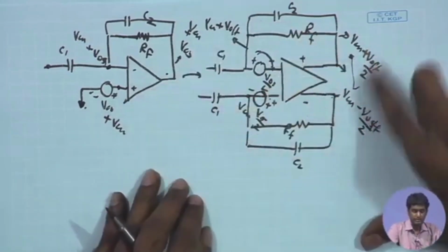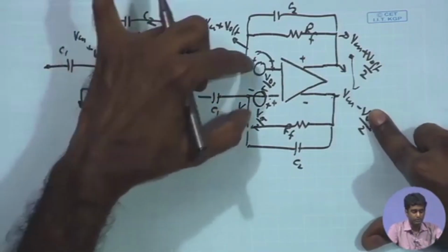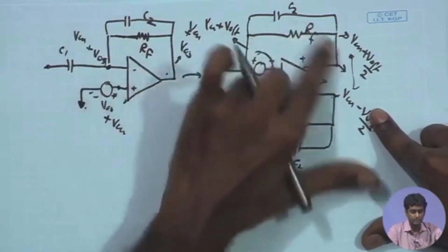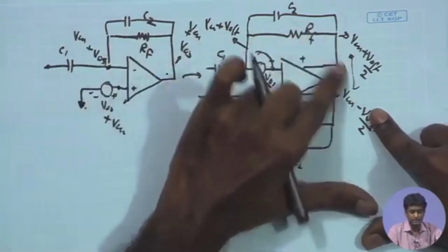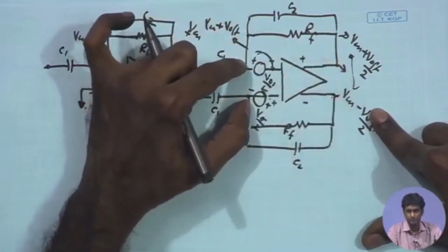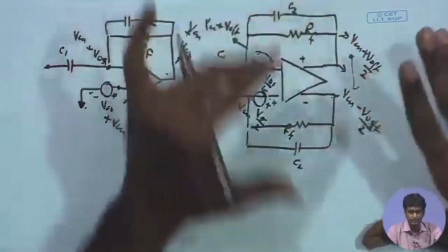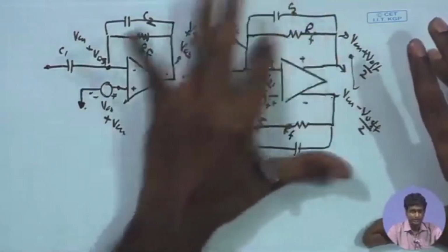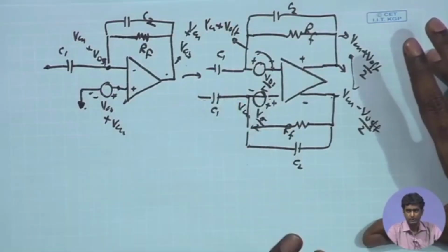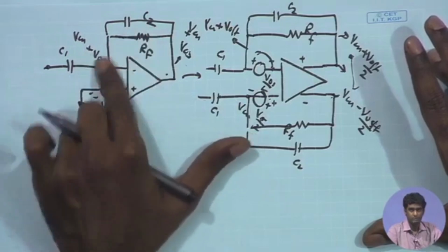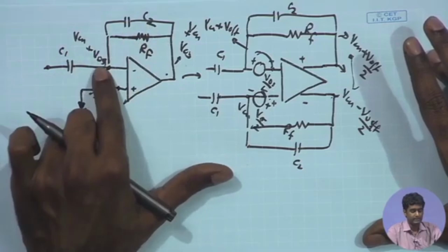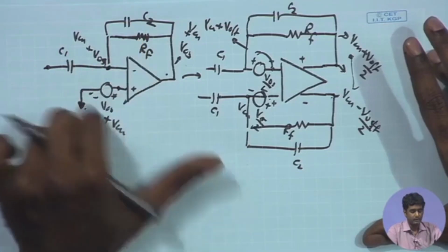So you have the difference just given by the V offset, corresponding to the effective input referred offset of the amplifier. In the case of resistive feedback, the difference between the outputs is just equal to the offset voltage, and therefore it is not magnifying that offset and saturating the amplifier. So this resistive feedback in fact is helping us take care of the offset also. And we can look at the transfer function also. If you look at the frequency domain transfer function for the feedback, there also you can see that ultimately the effect of offset is